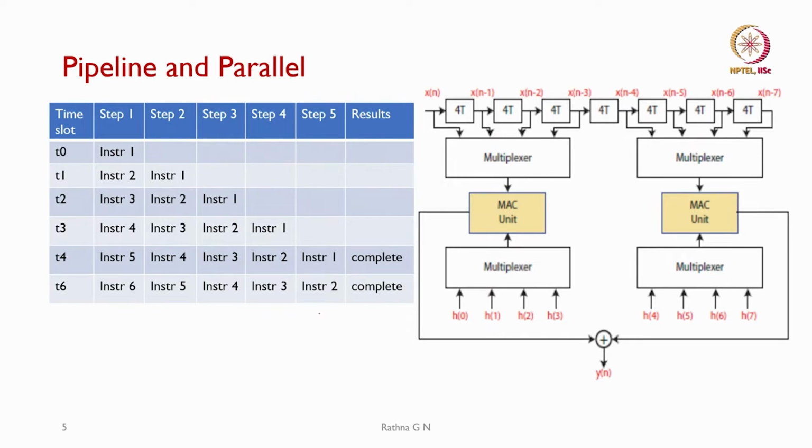So, in most DSP processors, we know that our add is going to complete in 1 clock cycle, whereas my multiply MPY operation is going to take 2 clock cycles.